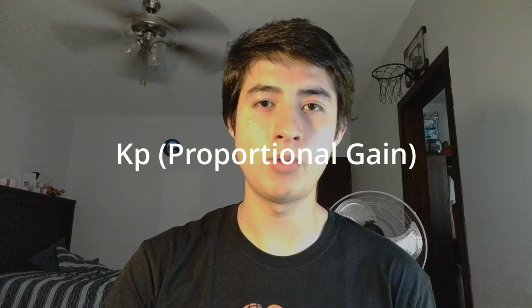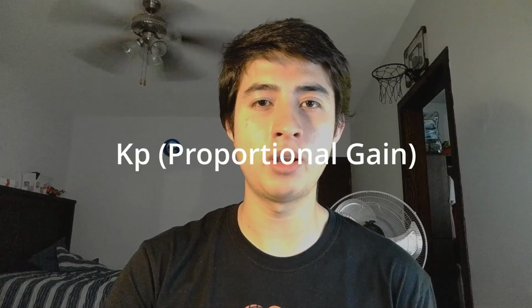There are three main parameters in the PD controller. The first one is the proportional gain. It's related to the proportion, so if you have a high proportional gain, you will have a more aggressive response from your PD controller, and if you have a lower proportional gain, you have a slower reaction. So it's important to find a value that is good enough to get to a target, not too aggressive but not too slow. You get me, right?